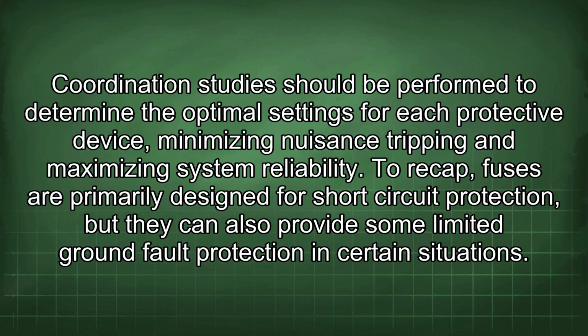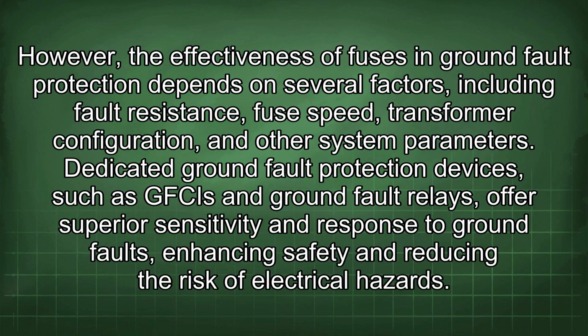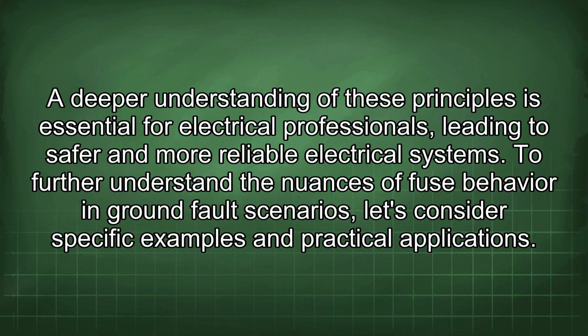in certain situations. However, the effectiveness of fuses in ground fault protection depends on several factors, including fault resistance, fuse speed, transformer configuration, and other system parameters. Dedicated ground fault protection devices, such as GFCIs and ground fault relays, offer superior sensitivity and response to ground faults, enhancing safety and reducing the risk of electrical hazards. A deeper understanding of these principles is essential for electrical professionals, leading to safer and more reliable electrical systems.